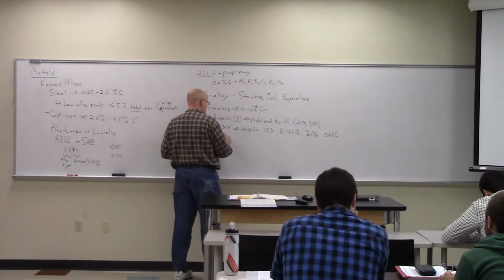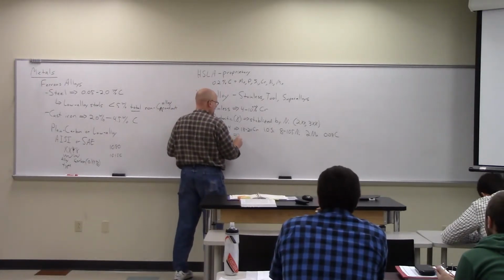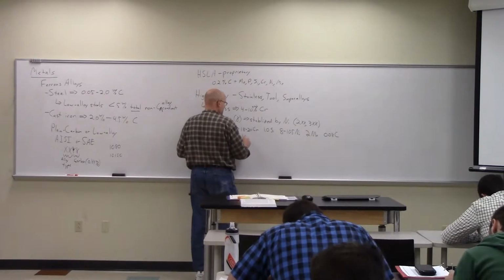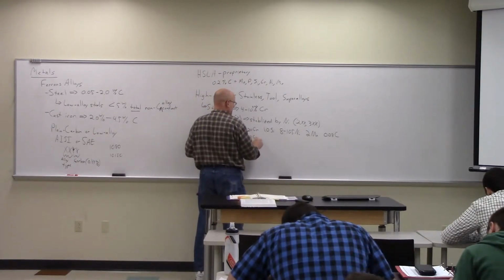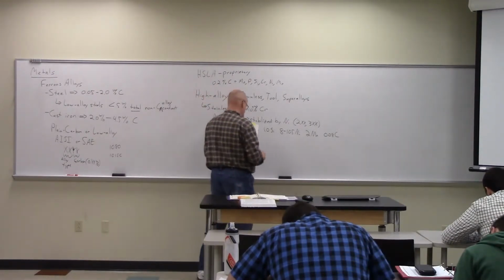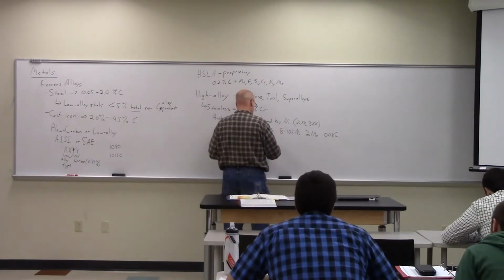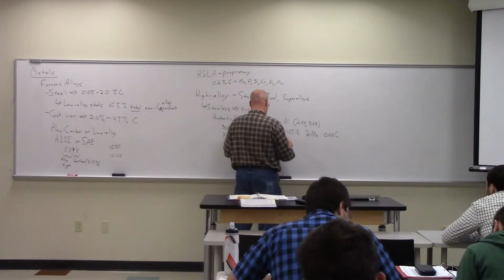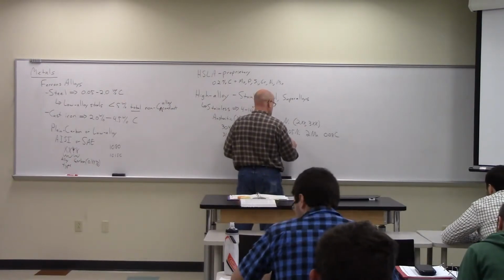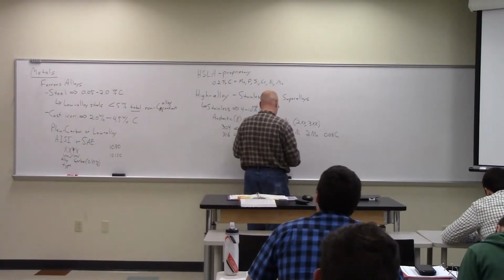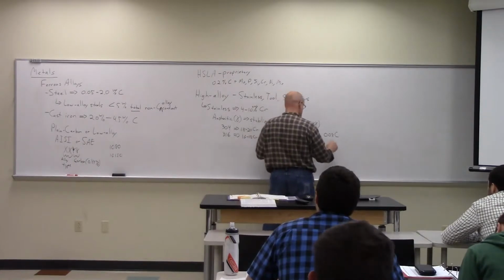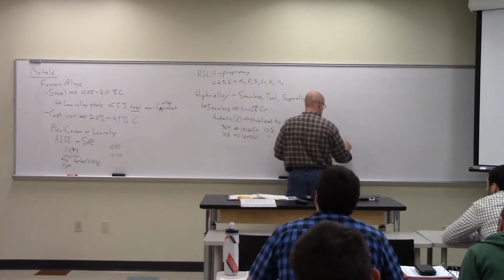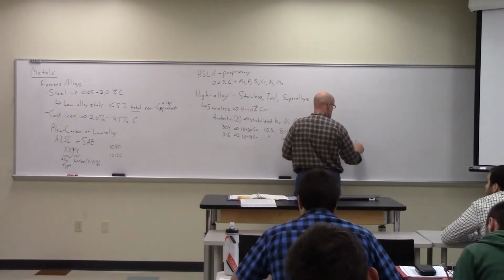And then there's 316 stainless, which has 16 to 18% chromium, so a little bit less chromium. Let's see here, same silicon. It's 10 to 14% nickel, so we have more nickel. Same manganese, same carbon, and 2 to 3% moly.